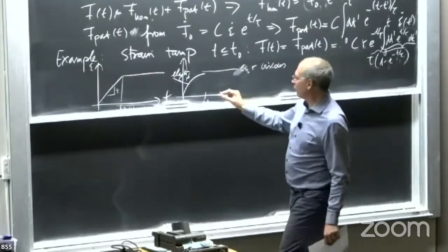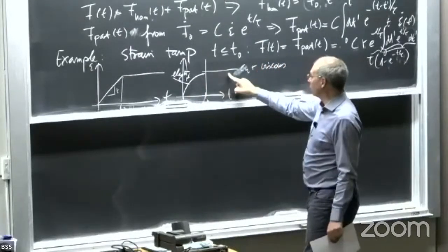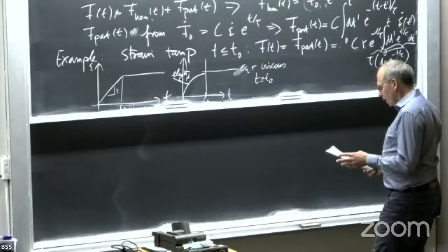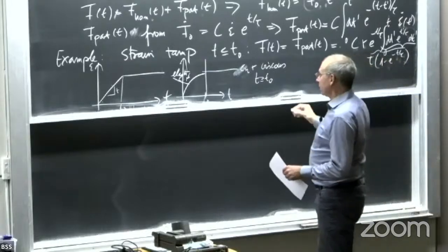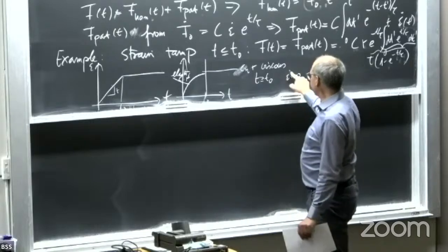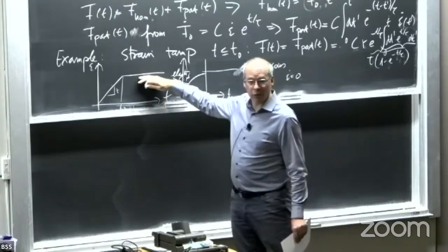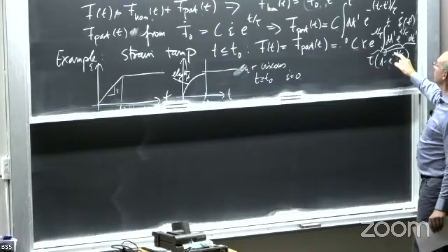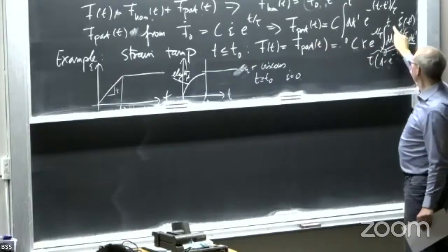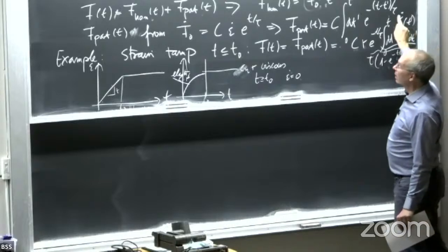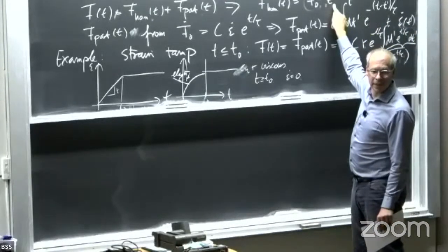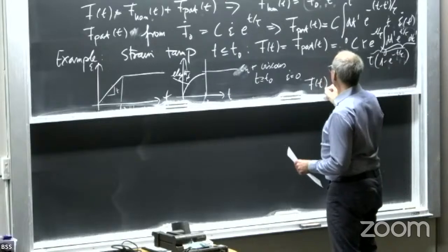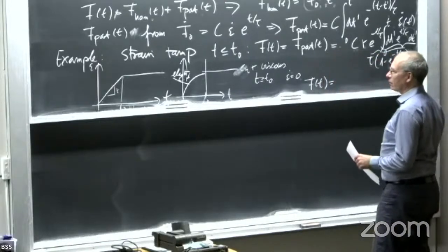So this is what we now found for the ramping part. Okay, now we go into the plateau phase. So now we go for t larger than t naught. In this case, the epsilon dash is 0. Okay, I'm in the plateau, no strain rate anymore. Therefore, this particular solution, this one, is 0. So the integral is gone. But we have our homogeneous solution. That's exactly the situation where the homogeneous solution kicks in. And therefore the f of t will be just the force which I have reached at this point here.